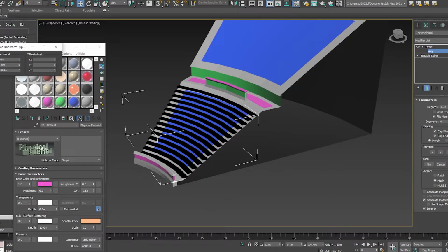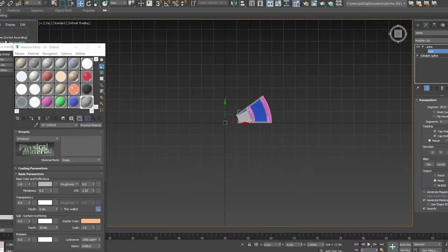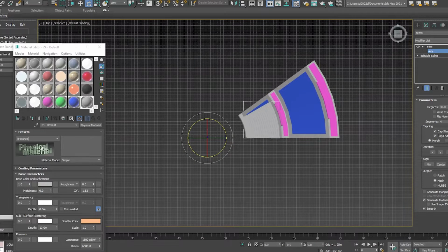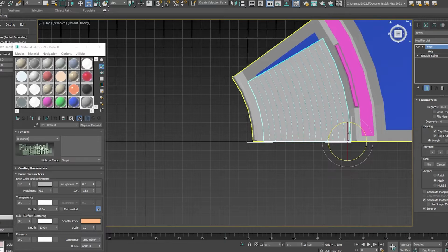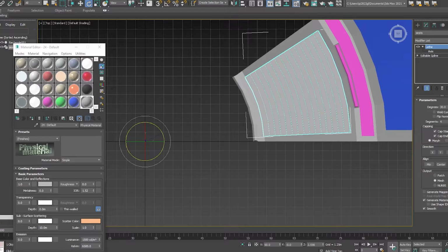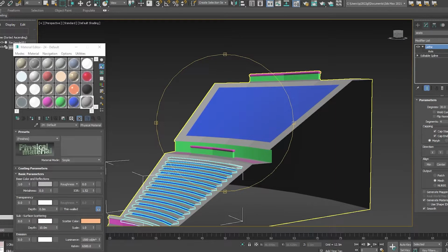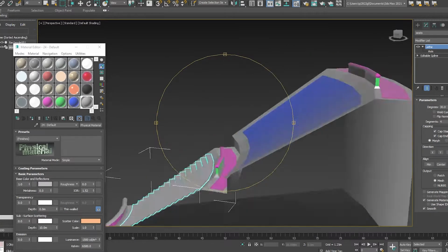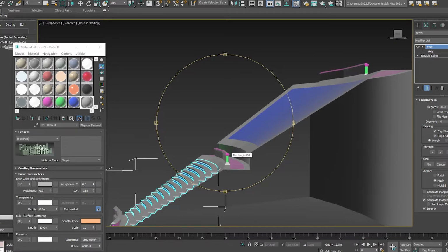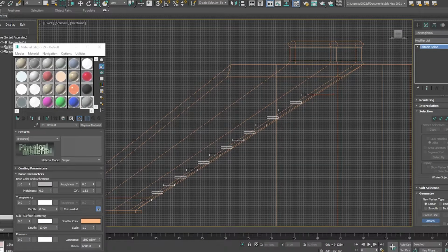These seats are going to be very light from a polygon count, and I'm taking the same approach with the seats that I did for the main foundation of the seating area, in that I've drawn a spline that is just a bunch of rectangles, and I did an array so they're all nicely evenly spaced out. And then I swept them around this, in 3D Studio, it's called a lathe modifier. If you're doing Blender, it's going to be something else. Everything's got this same sort of thing where I can draw a line and I can extrude it, or I can lathe it around a point, make it follow along a path. A lot of these modeling concepts are the same from one application to the next.